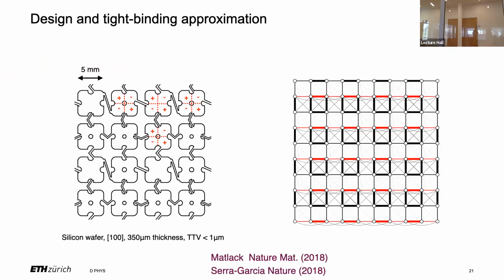Then you run through that and realize that not all modes have the same strengths of couplings, or some have two negative and some have only positive, so the arms attach at different places. So you actually also shift their frequencies a bit, and you start drilling holes to adjust for that. And then you have a working loop where you have a way to connect the geometry to the effective model. And I say going from here to here is trivial, and that's what you see here.